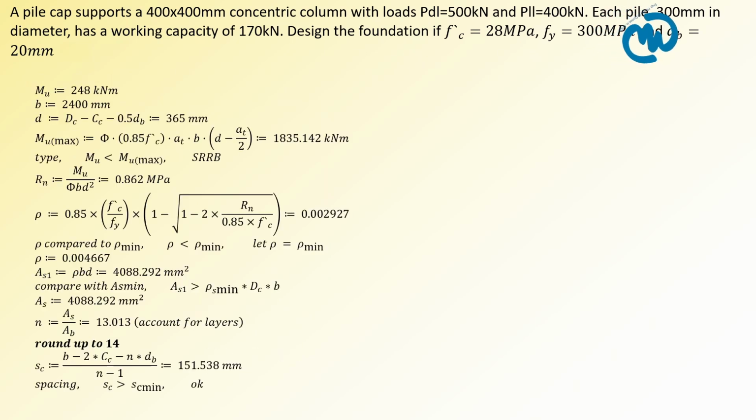Let's go through the flow of the calculation for the flexure design. While I won't delve into every detail here, as we've addressed similar examples before, I'll focus on key points. Specifically, the effective depth is calculated based on the assumption that the rebars along the x-axis are positioned in the lower layer.